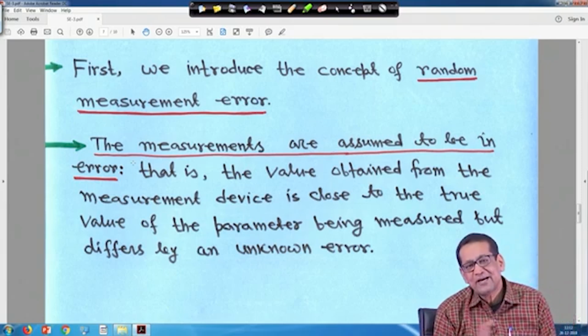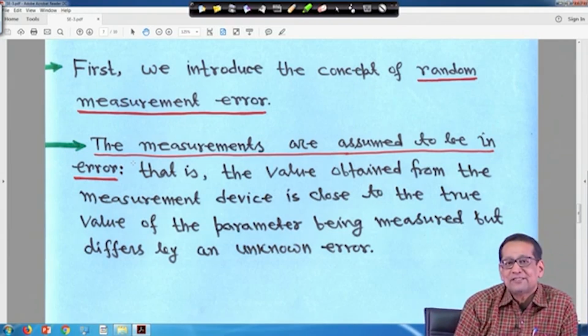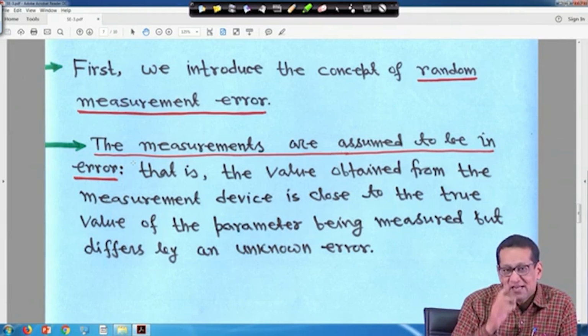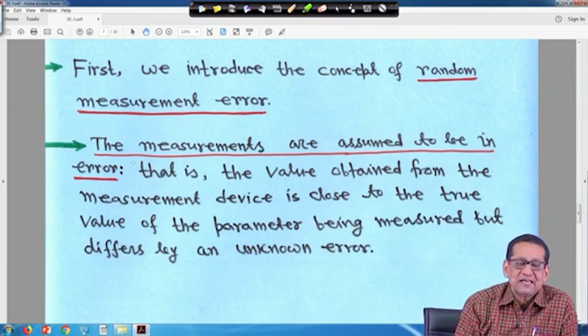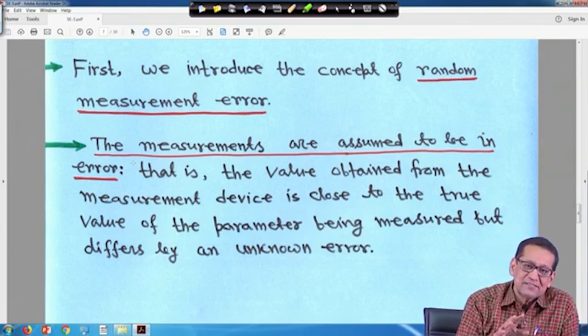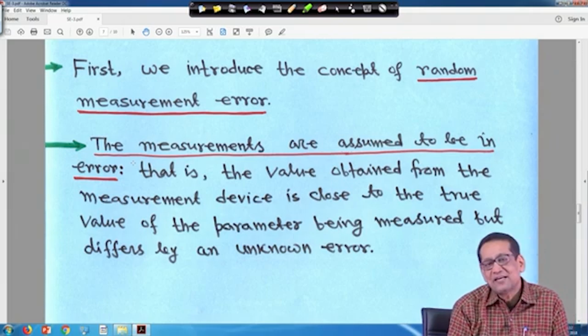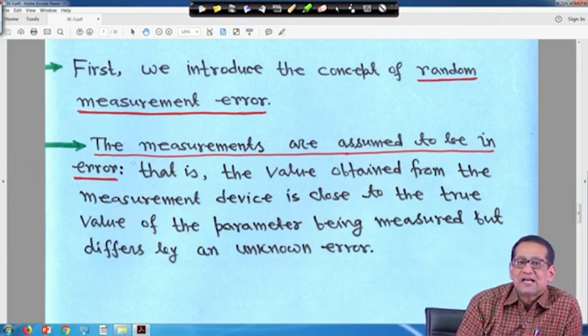Basically, you are taking the mean reading, right, because there is a true reading, but on both sides you will find the pointer oscillating. So, ultimately when it settles down, you are taking the reading, basically the mean reading. And on the ammeter or voltmeter, just check, the instrument accuracy will be written somewhere. Suppose it is written that accuracy is plus minus 3%, that is actually 3 sigma equal to plus minus 3%, right, for the standard deviation.